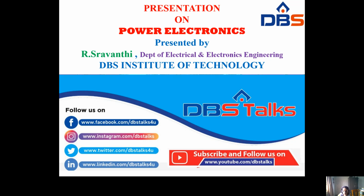Okay, so it comes to 0 at pi, and again increases at pi plus alpha in the negative direction, and it becomes 0 at 2 pi, and again increases at pi plus alpha. Okay, at pi plus alpha it increases and decreases at 3 pi and increases at 3 pi plus alpha in the negative direction. So this is the source voltage, and here is the thyristor T1 voltage.